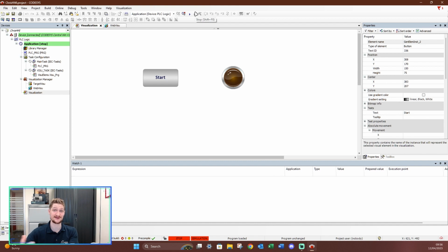Similar to when I pressed the start push button before, the output turned on. Well, again, you can do this via the HMI, but you very rarely want the HMI to operate things. The HMI isn't for control of a process, so to speak. It doesn't latch outputs on or unlatch outputs. That's through the PLC program.